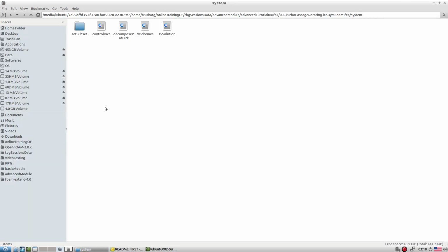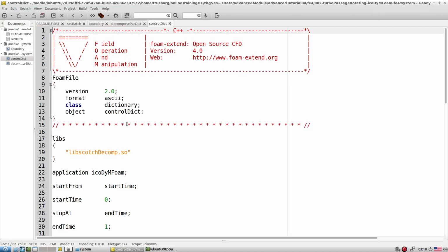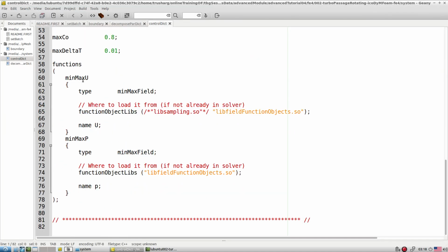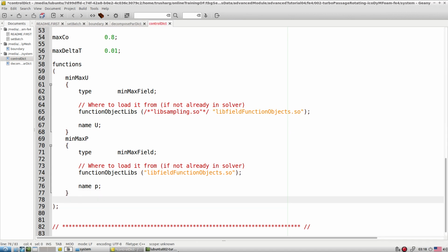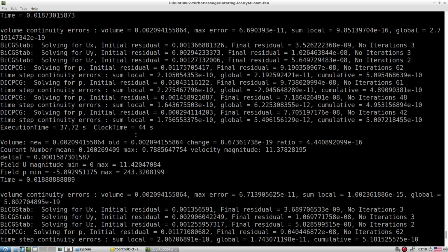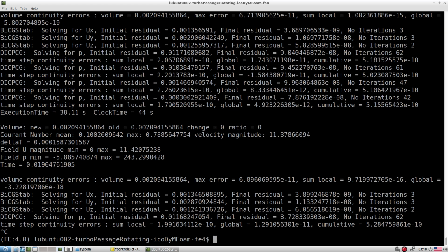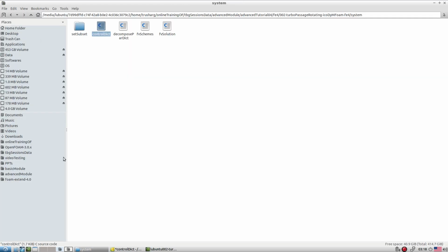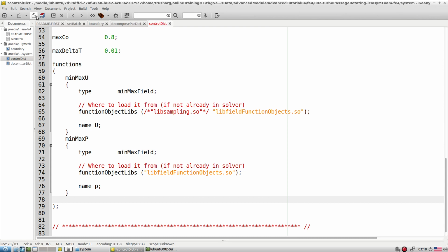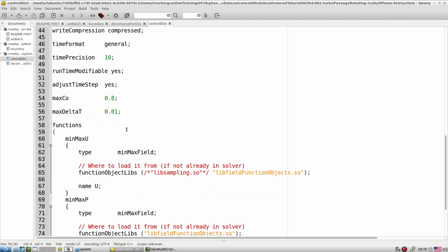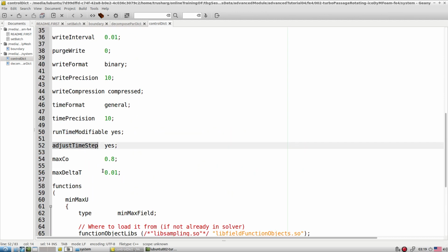What I mean is, if you look at the controlDict file, and we specify the GGI check, then it gives you an idea about the interpolation between all the GGI patches. If you require, you can type the GGI patch. That is sometimes very useful to look at the interpolation between different patches. If you want, you can copy that GGI check from the previous tutorials and keep it here. We have an adjustable run time, and we make sure the core number is reasonably low.